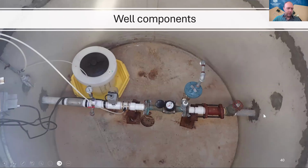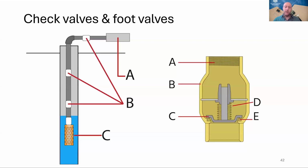So if you go through and look at what these all are, this is a check valve. This allows water to flow in one direction. We talked about this earlier, but just to look at it a little closer, this is an example of what it looks like. There are all kinds of different contraptions for how these work, but this is a pretty basic one. The water flows up and it can flow this way, but if it tries to go the other way, there's a spring that closes the valve, and so it doesn't allow water to flow down.